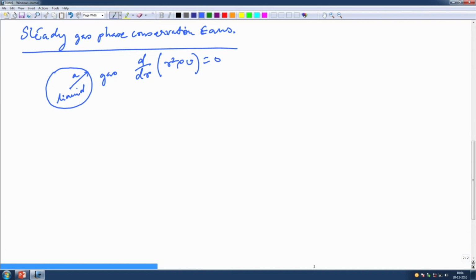The next equation that we are supposed to write is the species equation. Though it is a single component in the liquid phase, as the vapor comes to the vapor phase, it is a multi component system, because there is fuel and then there is air. The species that is evaporating, is evaporating into the ambient, which is air. So, you have to write the species balance equation for the vapor that is coming into the ambient. Under this assumption, we write the evaporating species as DYF.